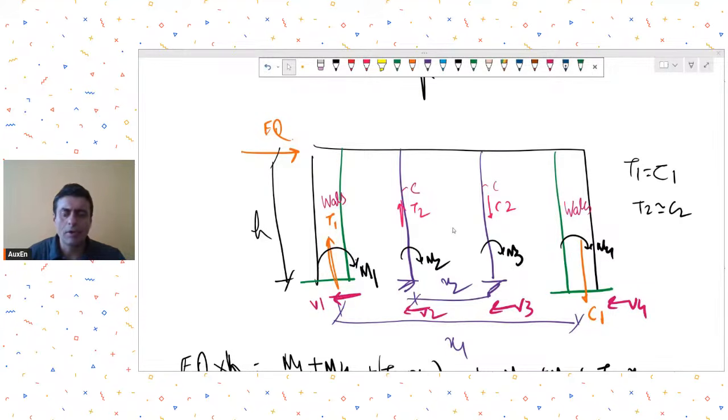If you are able to provide all frames, column-beam frames, then it will be more or less like a moment frame system. If you are not able to provide adequate frames and you have to provide RCC structural walls, but framing is not possible everywhere, then you may have to think about a dual frame system where you have frames plus walls.